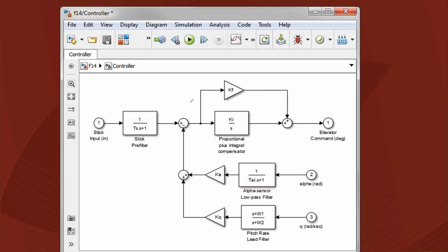So here in the graphical editor area, it's where you drop your blocks and you make the connections. These individual blocks represent individual phenomena or processes, if you will. So for example, here I have an addition block. What this is telling you right now is to add the signal that comes from here and subtract the one that comes from here.